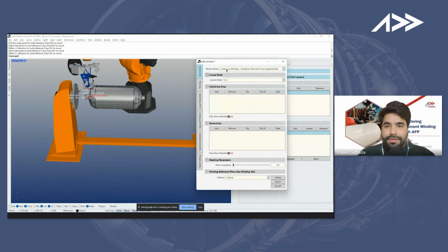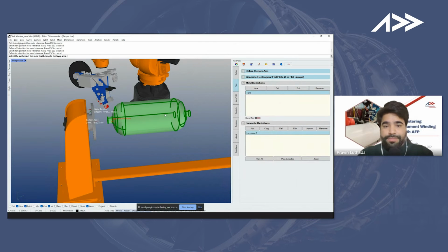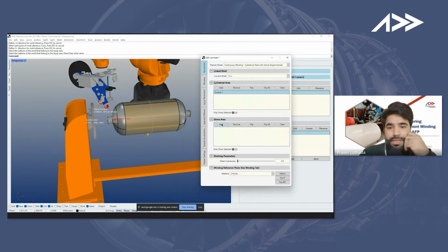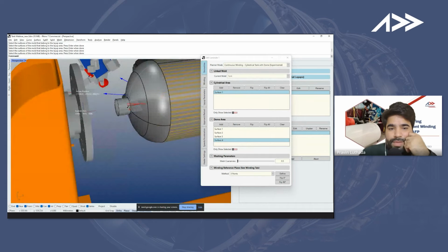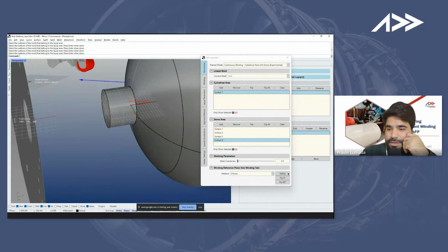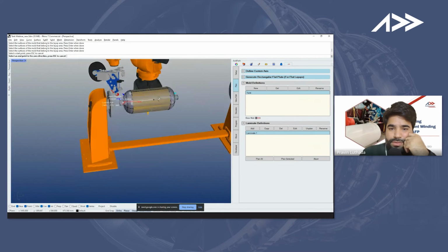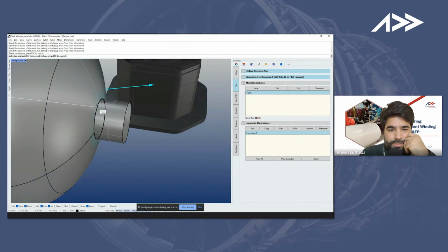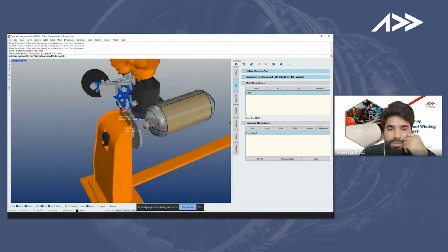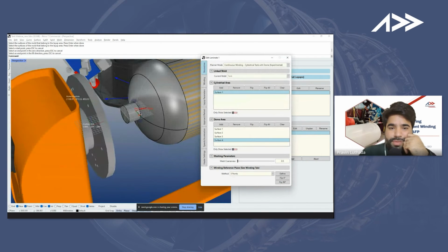So I can clear here. So let's start with selecting the cylindrical area as it is asking us to do. Then the dome areas. So we can select the dome areas. Then we have to select the directions. So I define usually the zero direction is pole to pole. And then the 90 direction is perpendicular. So my 0-90 is defined at the pole origin.